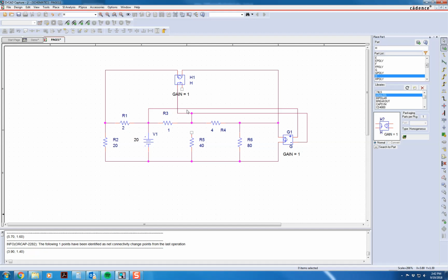Alright, so now we need to set the gain. So this gain is 35, and this gain is 3.125. And now we go ahead and set up our simulation profile. Do trans for transient. And remember, we're just doing a basic DC one here, so once the simulation profile jumps up here, there's not going to be anything we're going to need to add to it.